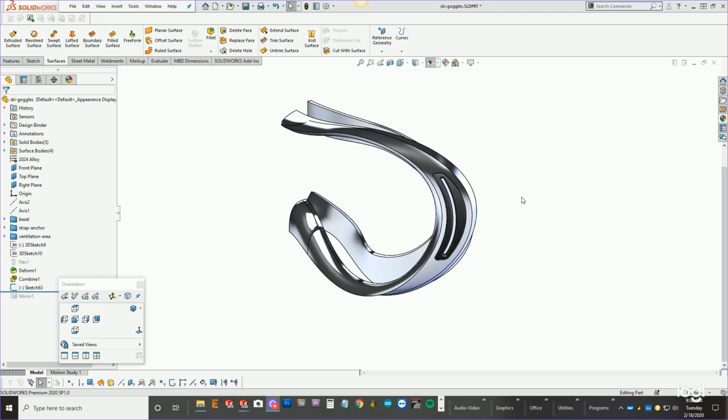There oftentimes is symmetry that will help you to be more efficient and do less modeling. And then the less modeling you do, the less features, and then the less features to actually go wrong. So that's what I mean by it being a robust model, when you can model 1/2, 1/4, 1/6, 1/8. Look for the symmetry.